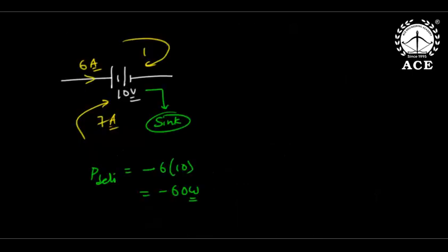After getting both I2 and I3, now the branch current in the 10 volts: I2 I got plus 7, so clockwise 7. I3 I got plus 1, clockwise 1. But the difference is 6 amperes entering positive. Now it is a sink. Power delivered is negative, since a sink delivering is meaningless. So power delivered is negative like that.